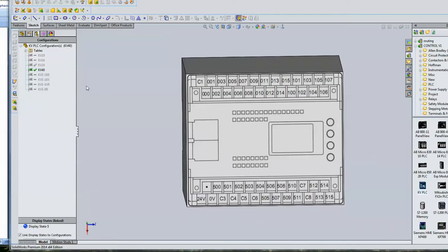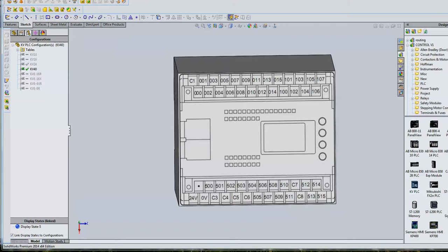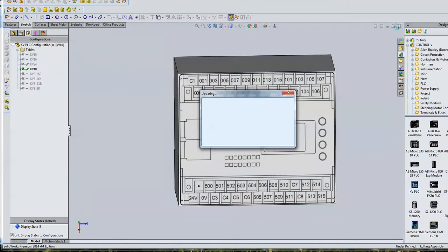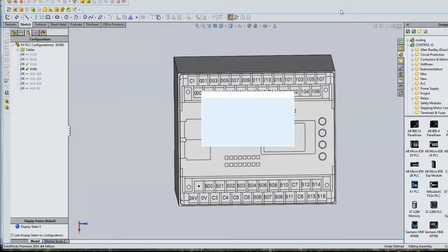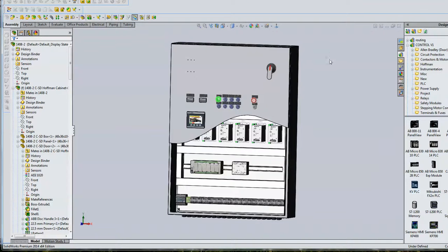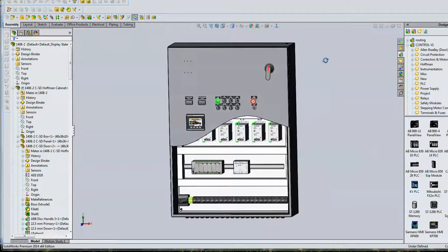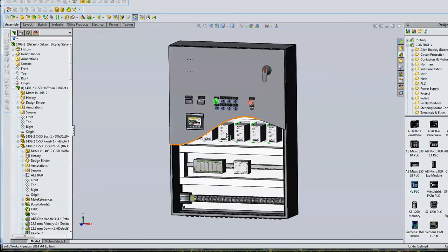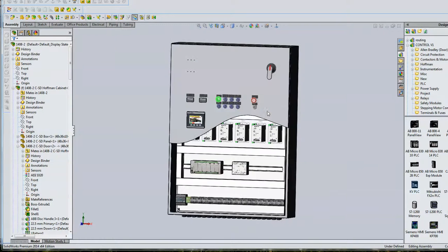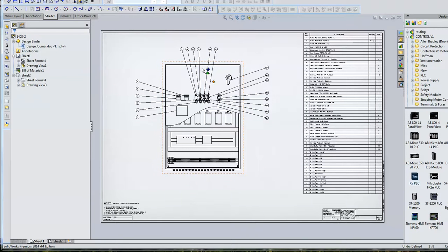But more importantly, when you place that into the control assembly, you can see that it's going to fit and how much room there is, which is the same thing that we did back with the 2D system. So we don't have much time savings there, but one of the things that these parts will do is we have custom properties, and we can put a description in there. And so by having that description in there, when we get done, we can then bring these views over into our drawing. With a couple clicks, we can create all the balloons and all the bill of materials.